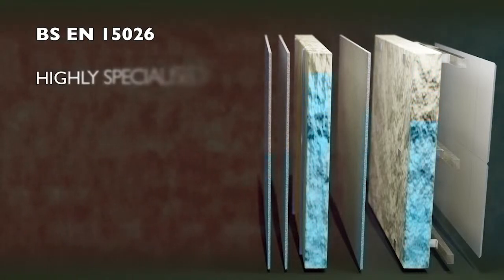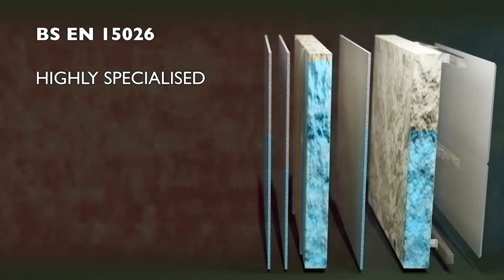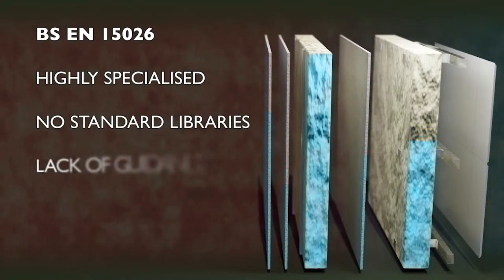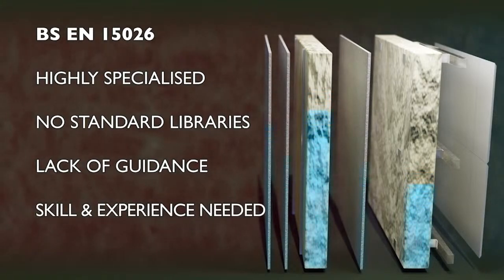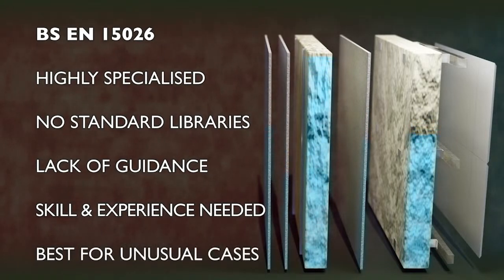This type of assessment is a highly specialised undertaking, and there is very little in the way of standardised material properties or guidance available to follow. This means anyone using the calculation software such as WUFI must have sufficient experience in the use of the data available to them and ensure any assumption regarding material properties are appropriate to the application under consideration. A degree of skill and experience is also necessary to properly interpret the results of the calculation. So whilst BS EN 15026 is a powerful tool, it's far better suited to use on particularly unusual, high-risk or